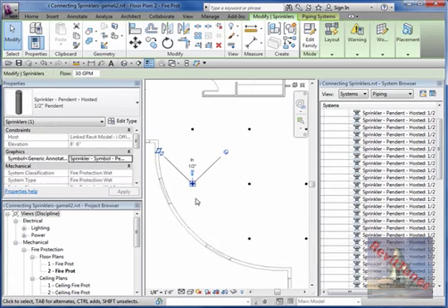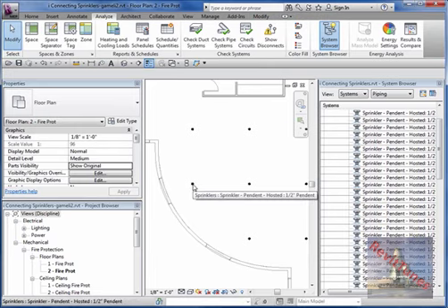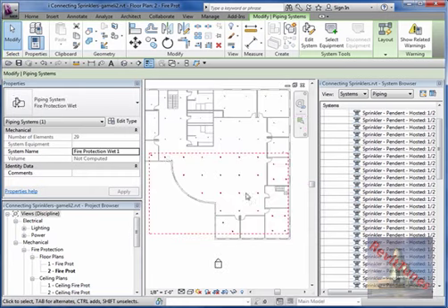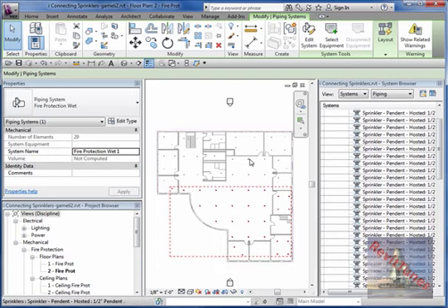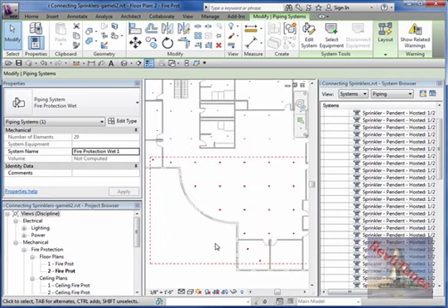If I deselect the sprinkler, I put my mouse on tab and I hit tab, and I click after the tab. You see this red frame? It shows me which of those fire protection sprinklers are connected in one analytical system, in one logical system. Software calls it logical system. If I hit in one of those tabs, nothing happened, because those are not assigned to any logical system. So that's one way to verify which objects belong to a logical system.